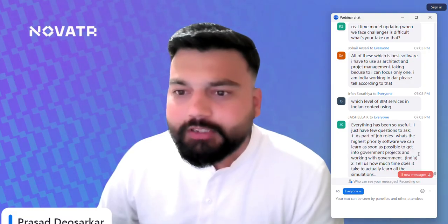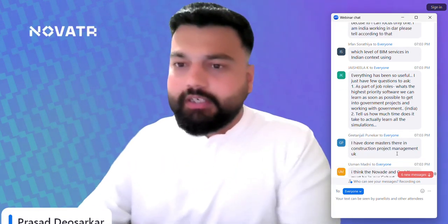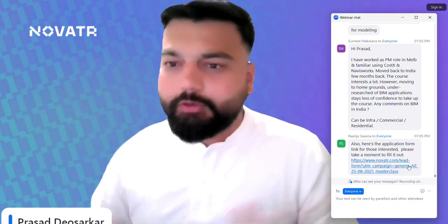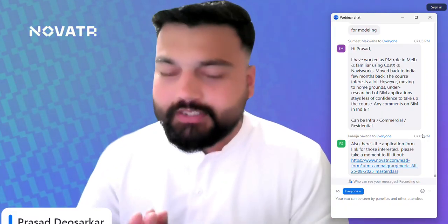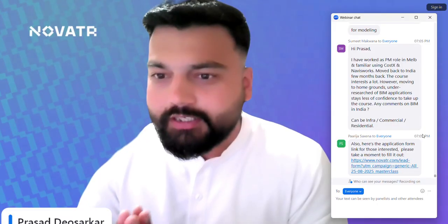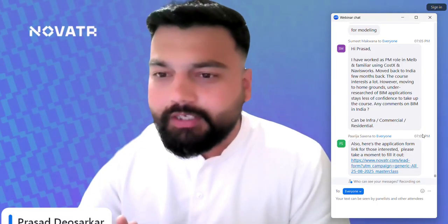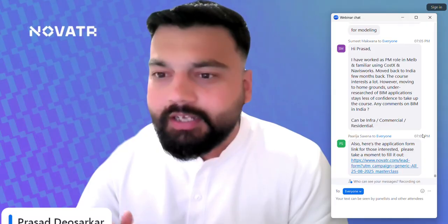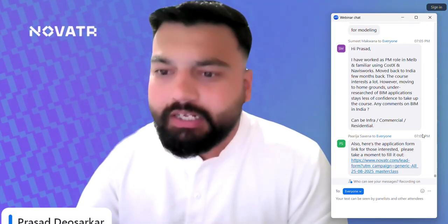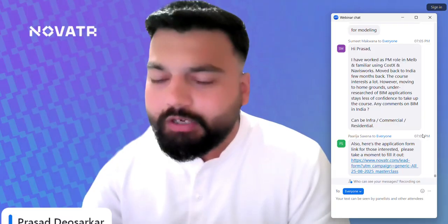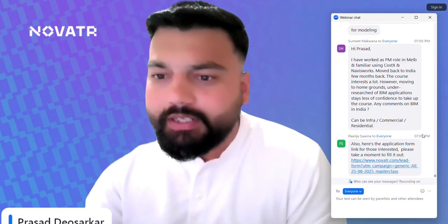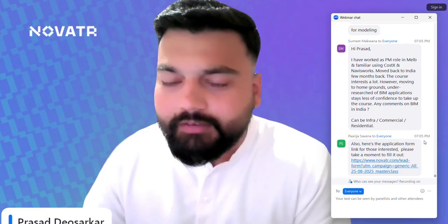Can we do complete cost estimation using Navisworks, Dynamo, or are these only for planning? So no, I think your question is a bit all over the place. Navisworks is something that you use for clash detection, coordination, 4D simulation, 5D cost estimation, and in general visualization. Dynamo is a programming language that you use to automate repetitive tasks.